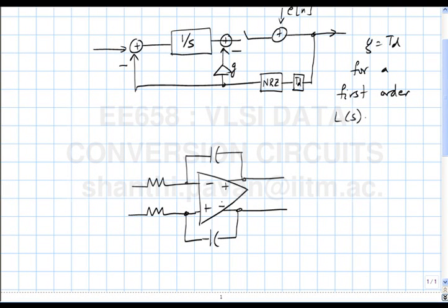How many inputs should the integrator have? Look at the block diagram and tell me. It is basically subtracting two signals and integrating the result. So this is a 2-input integrator. So let me say this is 1 ohm, 1 farad, and please remember the reason why I told you it makes sense to do everything at some normalized sane frequency, which I have chosen to be 1 hertz.